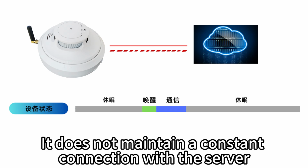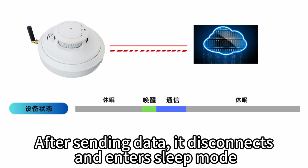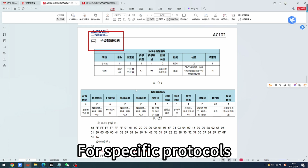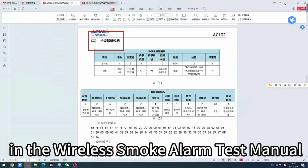It does not maintain a constant connection with the server, only connecting when transmitting data. After sending data, it disconnects and enters sleep mode. The uploaded data is in hexadecimal format. For specific protocols, refer to Section 2.2 Protocol Parsing in the Wireless Smoke Alarm Test Manual.